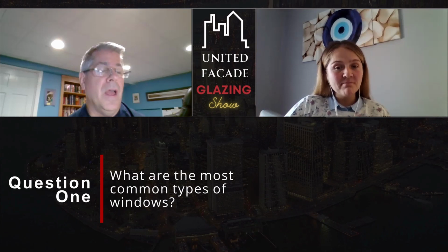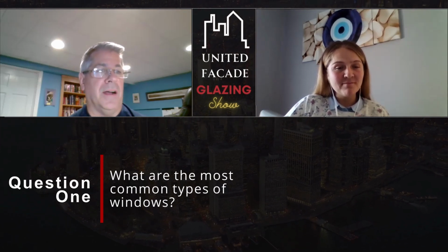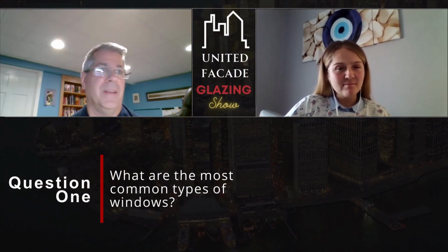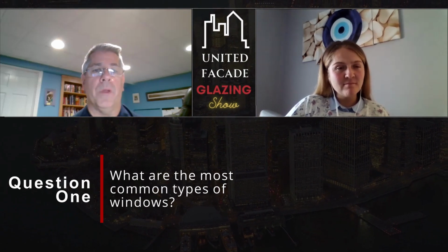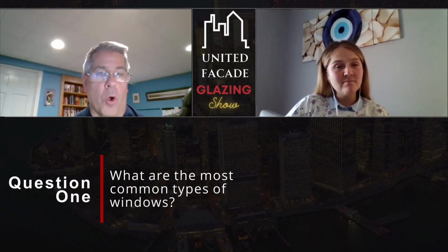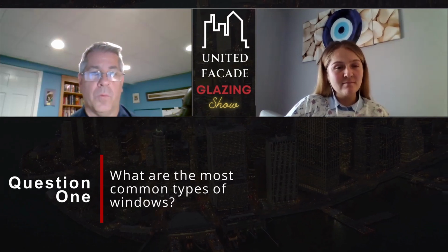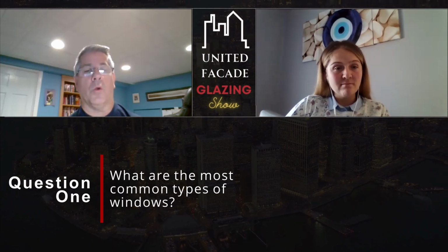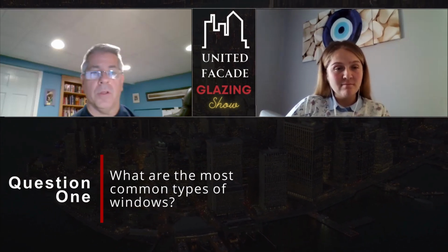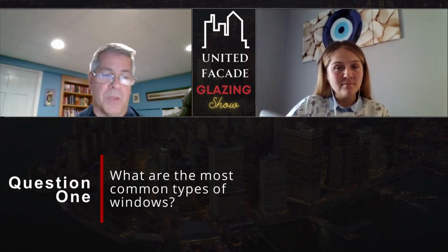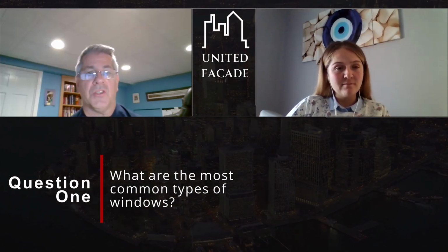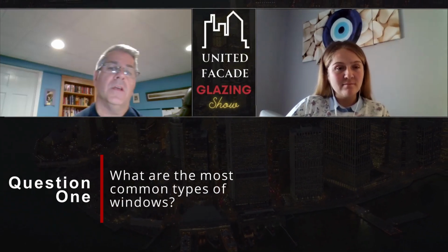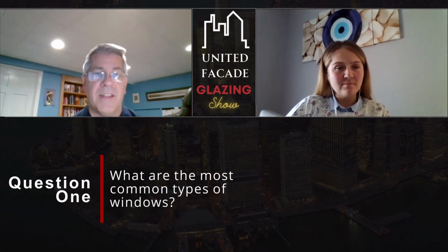A casement window you would want on a high-rise building that's going to be anything above probably 10 stories tall to open inward. If you had an outward open casement window, you can get a gust of wind, especially in a city like Manhattan or Chicago or LA, where you have what you want to call wind tunnels. You can get wind going down between buildings and it picks up speed between the windows. If you have an outward swinging window, the outward swung window could be caught in a wind drift and shear off its hinges or overextend its hinges.